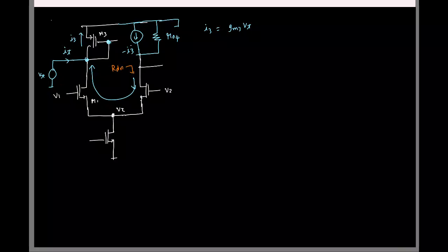If we assume R0 for all transistors, what is it? It's a cascode, right? Don't simplify, just tell the exact expression. It's R02, this transistor M2, plus the impedance looking here. What is the impedance looking here? 1 by GM, because this drain is short, right? So that is 1 by GM1 plus GM2 R02 times 1 by GM1, and the two GMs are equal, so this is as good as 2 R0.